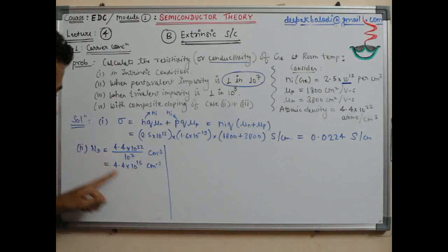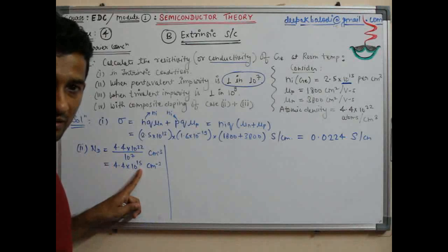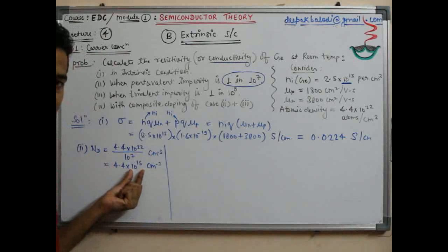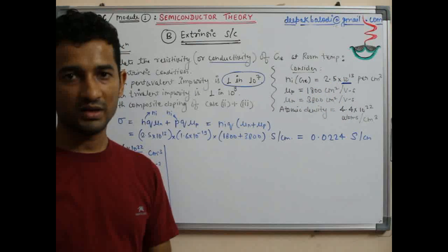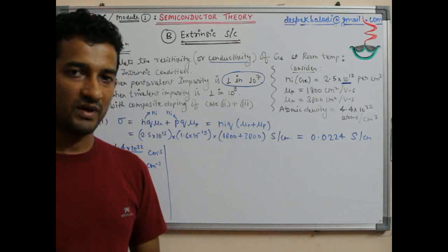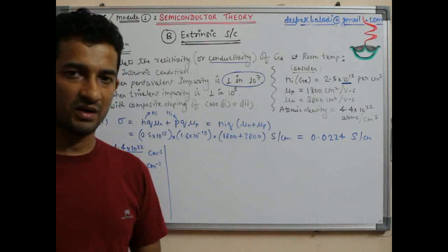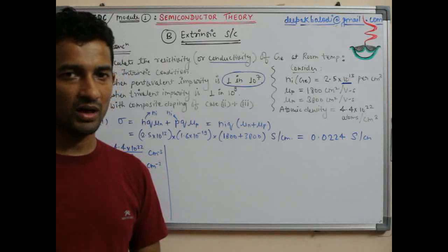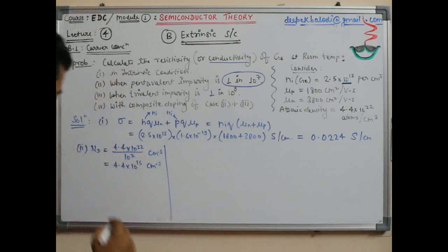But with the impurity concentration, the additional electrons from external doping go to 10 to the power 15. So 10 to the power 15 is definitely 2 orders greater than this. So we should not be in doubt whether we can neglect ni or not. Definitely we can neglect it. If anybody is interested in the accurate calculation, you can go for that square root formula.